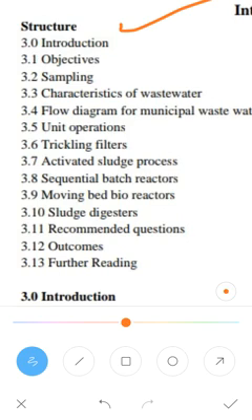The sample volume should be small enough to be transported, and large enough for the required analytical purposes. Because of the increasing emphasis placed on verification of the accuracy and representativeness of data, greater emphasis will be placed on proper sample collection. For the preservation techniques, laboratory personnel often help in planning, and the sampling programs will be carried out in consultation with the lab and the user of the test results.